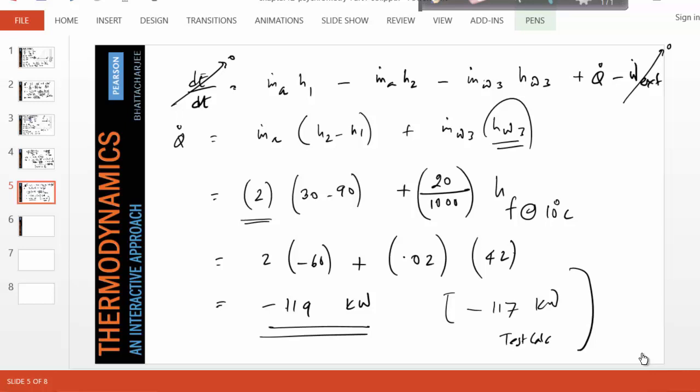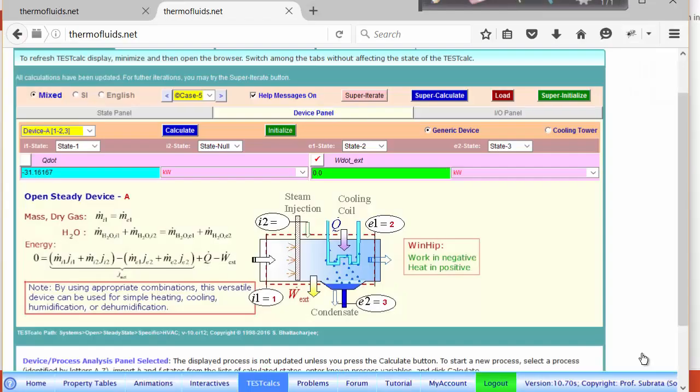You have to remove heat by a refrigeration unit. So whatever you're paying for your refrigeration of 117 kilowatt, now you have to do only 30 kilowatt. So your cost of cooling will go down to 1/4 the original value, not half. Why is that? Because this whole exercise is to bring out that when there is condensation, you pay for it heavily. So if you air condition hot air in a very dry place, say in Las Vegas or Phoenix, and so there is no condensation, there is very little penalty for cooling air.